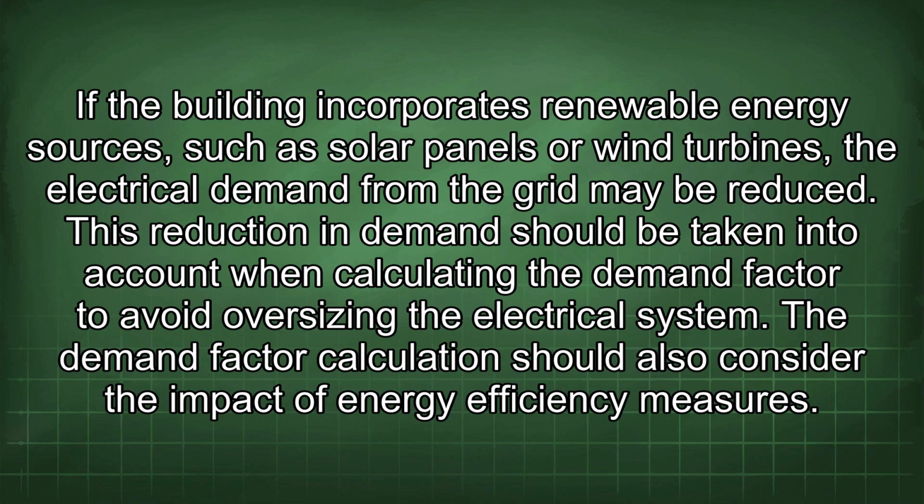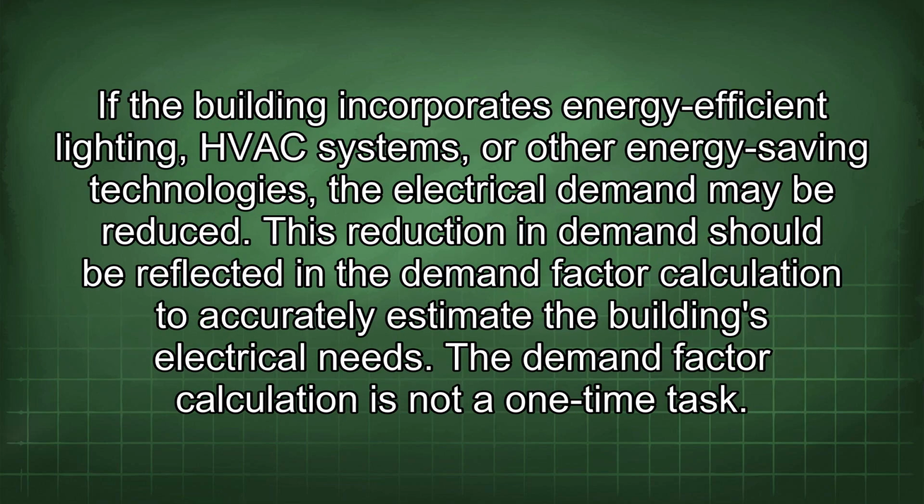The demand factor calculation should also consider the impact of energy efficiency measures. If the building incorporates energy-efficient lighting, HVAC systems, or other energy-saving technologies, the electrical demand may be reduced. This reduction in demand should be reflected in the demand factor calculation to accurately estimate the building's electrical needs.